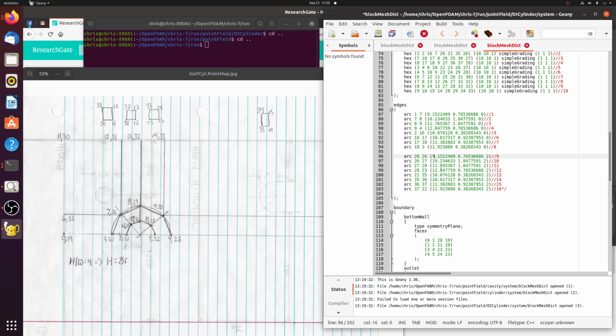And what I need is an interpolation point, and I say halfway, so halfway between here and here is half of this angle, so that's 22.5, and I'll bisect it in half. The angle 22.5, and this length right here is 2 centimeters, because this length right here is 1 centimeter and this is another 1 centimeter out, so it's 2 centimeters.